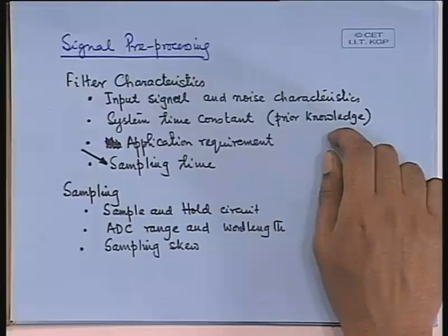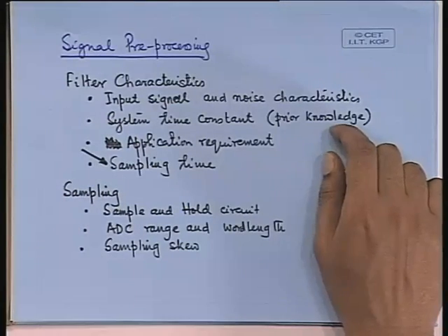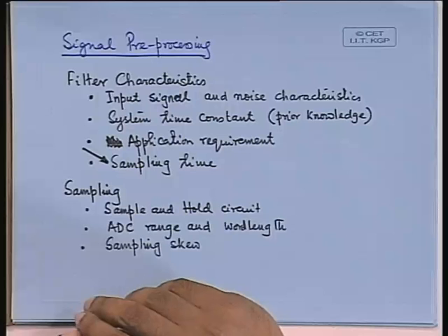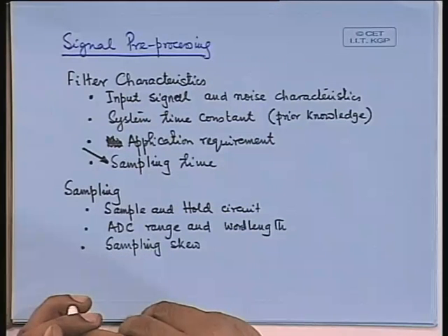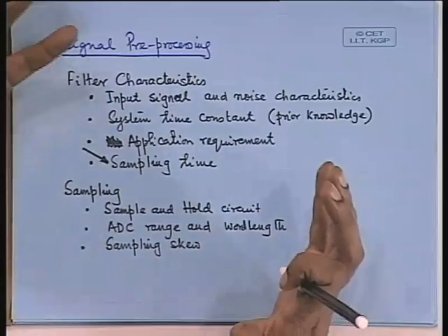Similarly, consider sampling time design. What does sampling time design depend on? It depends on the model bandwidth, on the expected system bandwidth. Why? Because if you know the aliasing phenomenon, then if you have chosen your sampling frequency too small, what is the problem with aliasing?